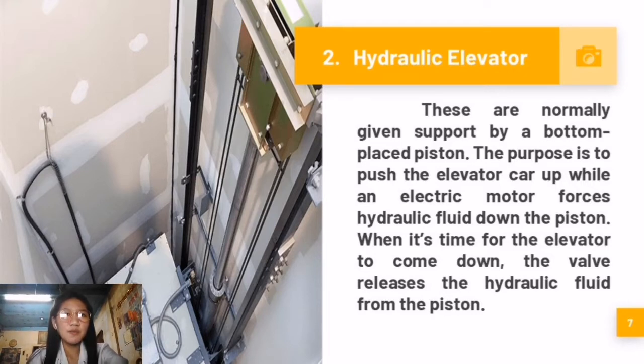The main reason hydraulic elevators are popular is because they are more affordable to set up and still have relatively lower maintenance costs when compared to other elevators. Hydraulic elevators utilize more energy because they use an electric motor that works against gravity. You should regularly check the hydraulic fluids because a small leak could easily lead to a catastrophic event or become an environmental hazard. And hydraulic elevators are classified into three: the roped, conventional, and holeless hydraulic elevator.